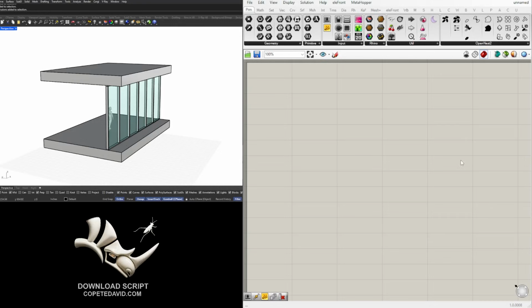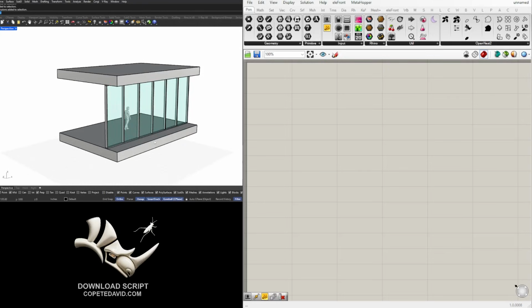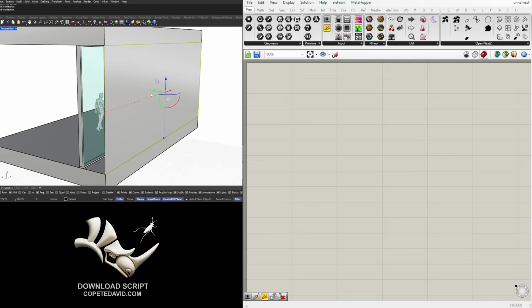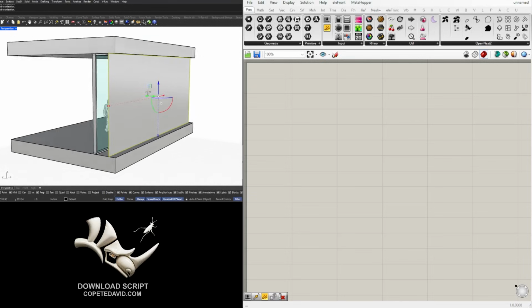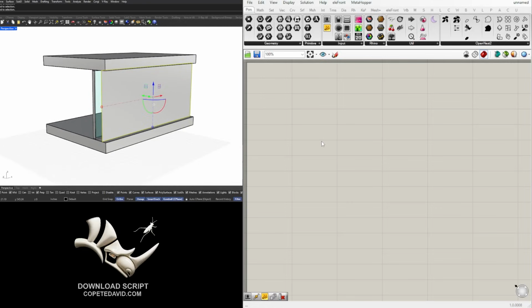So what we need to do is bring into Grasshopper a surface that will be what we will develop for this design. So what I'll do here inside of this model is go to extrude curve and extrude this up. Then I'll take this and bring it into Grasshopper. But first I will move this in, let's say by 1 foot.